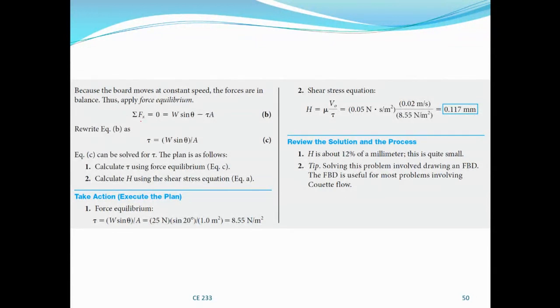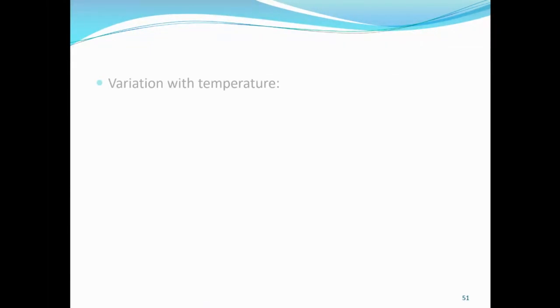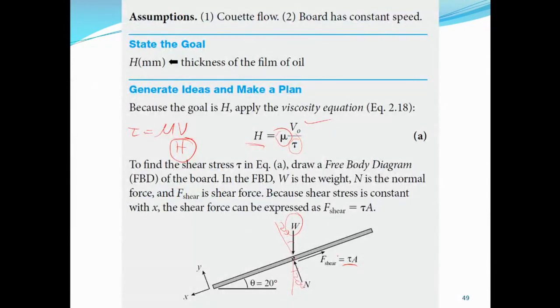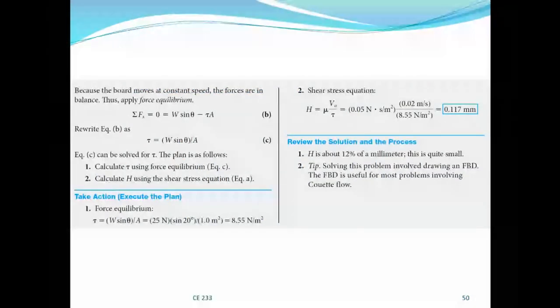Applying the equilibrium equation, summation of forces along this plane, we have W sin theta, if we call this angle theta, equal to the shear force F, which is tau A. This will enable us to obtain the shear stress.